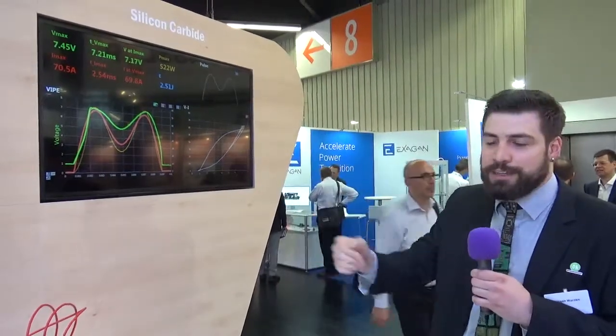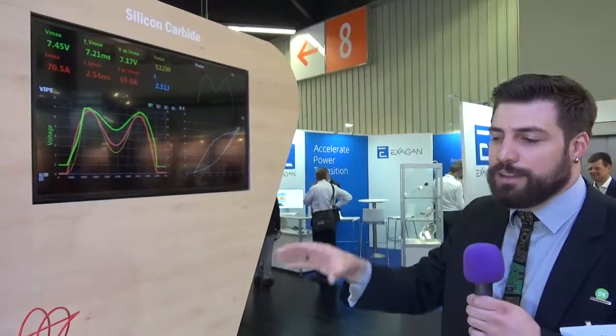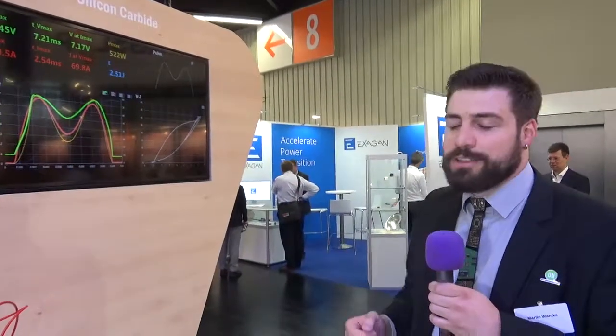This is due to the self-heating in this device, which will eventually also degrade the device and lead to failure if the current is going too high. That's why we have this tester to actually guarantee values of currents and peak currents that will help us determine the SOA of the device.